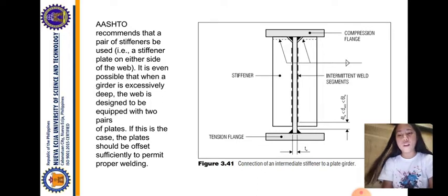When a stiffener is attached to only one side of the web plate, AASHTO requires that the stiffener must be in bearing against, but need not be attached to, the compression flange in order to be effective, according to AASHTO 10.48.5.3. An exception to this rule would be if the stiffener plate were also acting as a connection plate for a secondary member. See Section 3.11.2, Part 5, Single and Dual Stiffeners.